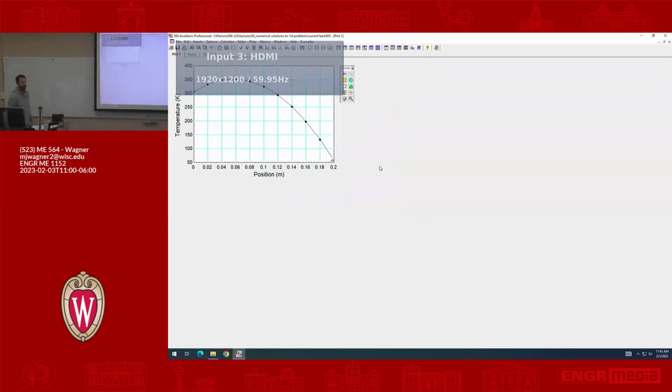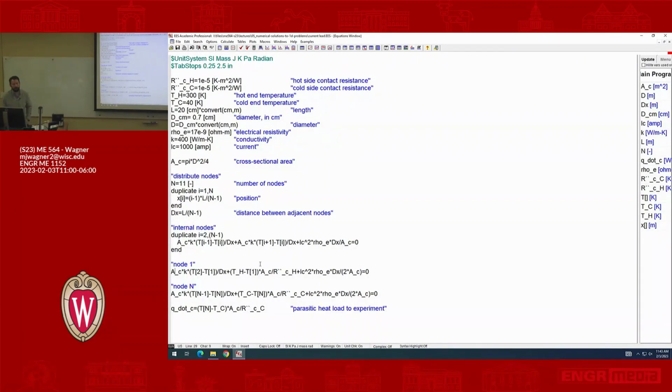So how do you determine mesh independence of the solution? Yeah, that's a great question. So what we would look at here is, let's go back. What is it that in this problem I actually care about? Do I really care about the temperature of the wire? Probably not, unless I'm worried about it melting. What I actually care about is, like I said, the heat flow from the wire into my experiment.